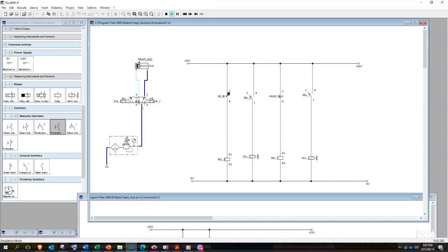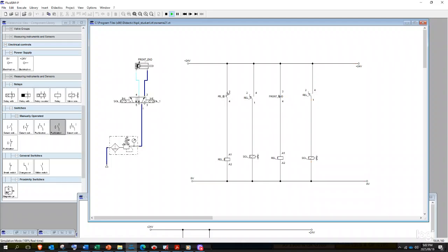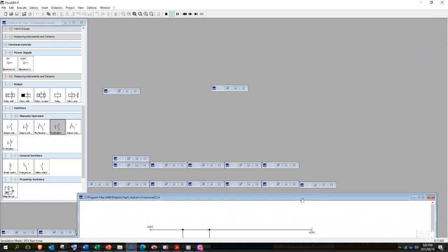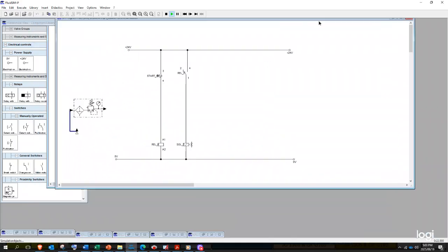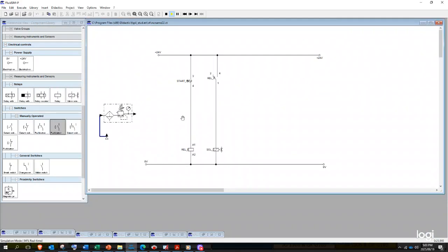We don't need any sensor or position detector, right? We only need a sensor or position detector for retracting and not for advancing. So here we need that position detector or sensor, which is our limit switch, to advance. So we go to our make switch. Since our make switch is an actuator, we connect it directly to what? To a relay. It is our input.